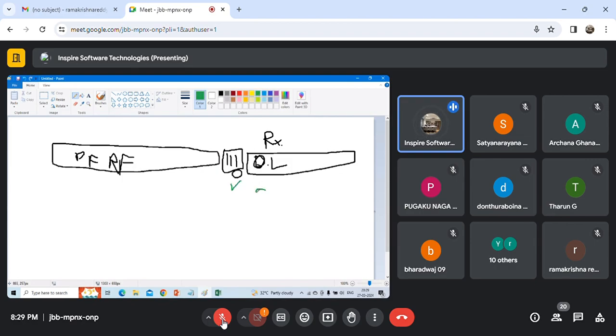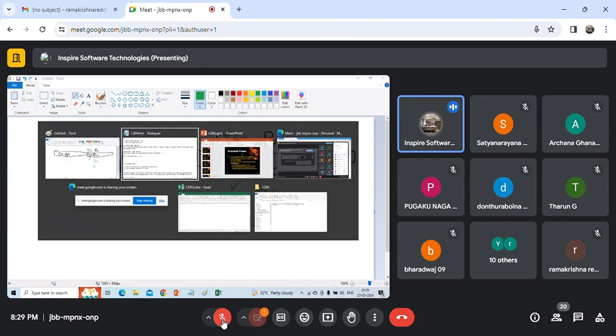Overload frame will be sent in 2 cases: when the receiver wants the transmitter to hold the next message, or when it sees a dominant bit in the interframe space. In either condition, the overload frame will be sent. Is it clear?